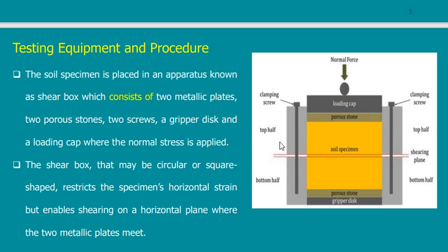Suppose when I put the horizontal load, I pushed it very quickly. What will happen? At the beginning, I left the sample an adequate time so that the required water left the sample. But when I put the load on the movable part of the specimen, I sheared it very quickly.